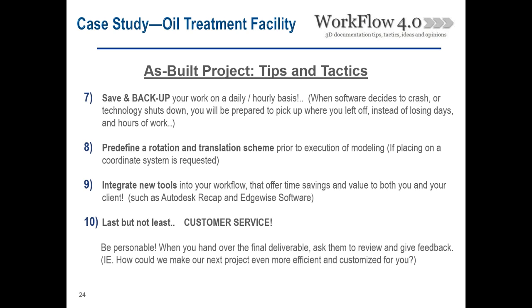It's set up so that if it's acceptable, it'll come through green, and yellow or red depending on what it overlays. But there aren't any real good quality reporting tools inside. That's why you kind of have to set up your own quality check with survey control or something. So some of that is still on a per service provider basis on how you can handle that quality reporting.